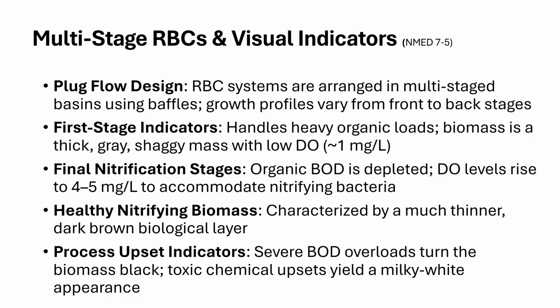So if it looks milky white, it's a toxic chemical upset, and that's if you're getting too much BOD coming in off of the primary clarifier. Okay, you're basically shocking the system at this point. So there are some good test questions here for troubleshooting.